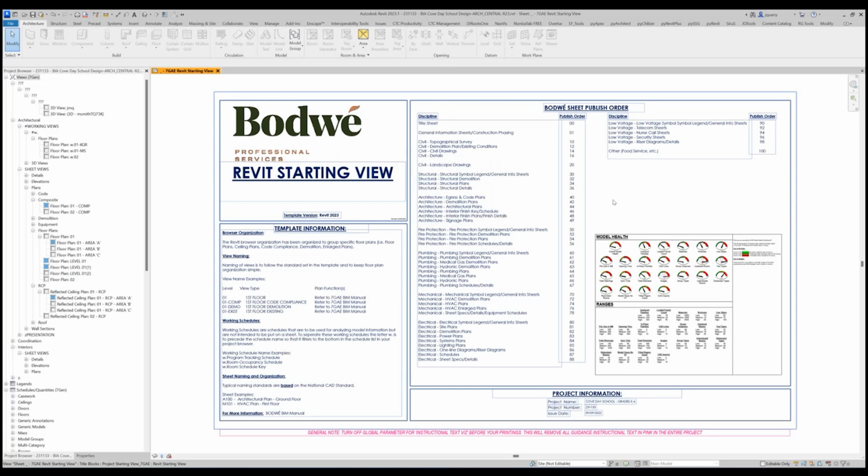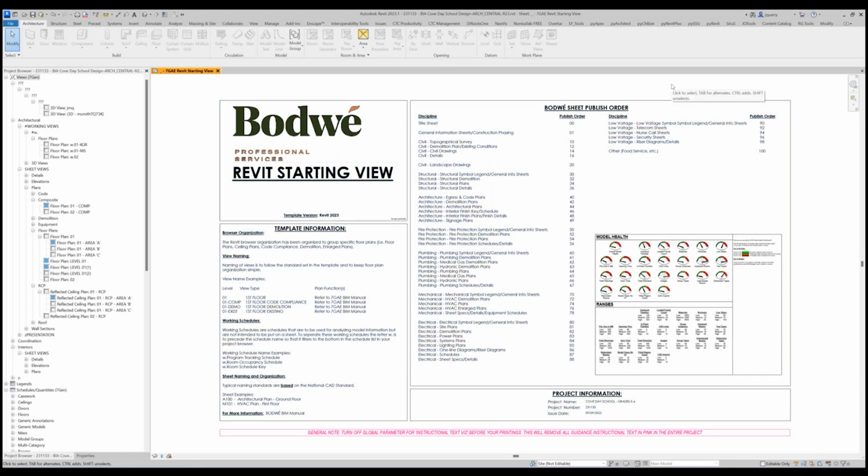All right. So as this is loading, I'll give you my spiel. I typically do all interior and all exterior windows using the curtain wall tool in Revit. And as I go through this, I'll show you the process and why the process is the way it is, because it'll save you time. I don't have many door types that have side lights. I have one that has one side light and it has the ability to split it horizontally, so there's one on top of the other. But other than that, I do everything as a curtain wall storefront and you'll see why.